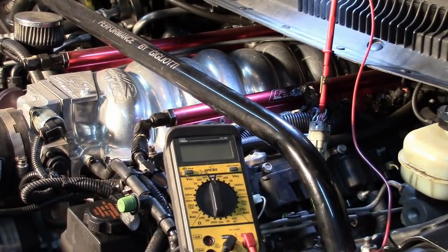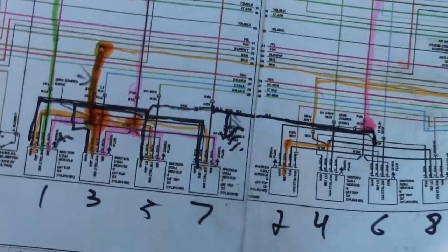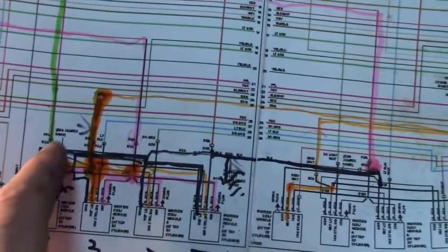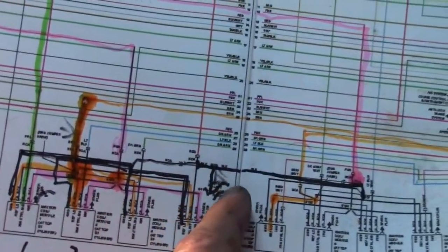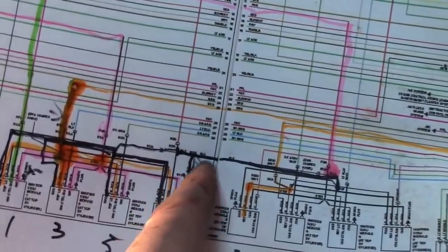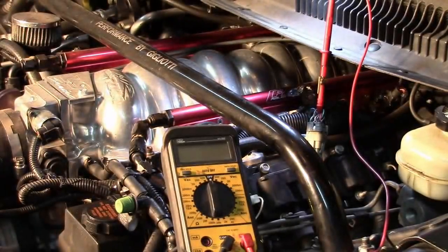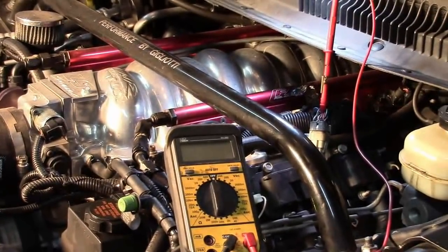Just double check our work on that. That is enough for me, but we're learning here. We look on our wiring diagram. We can see I just drew the ground in black. Of course, I almost always draw the grounds in black or green. And if we look at our grounds, here's our ground constant at the block, and we can see that it is a black wire. It does say black on there. So we have successfully, through function, identified our wire colors.